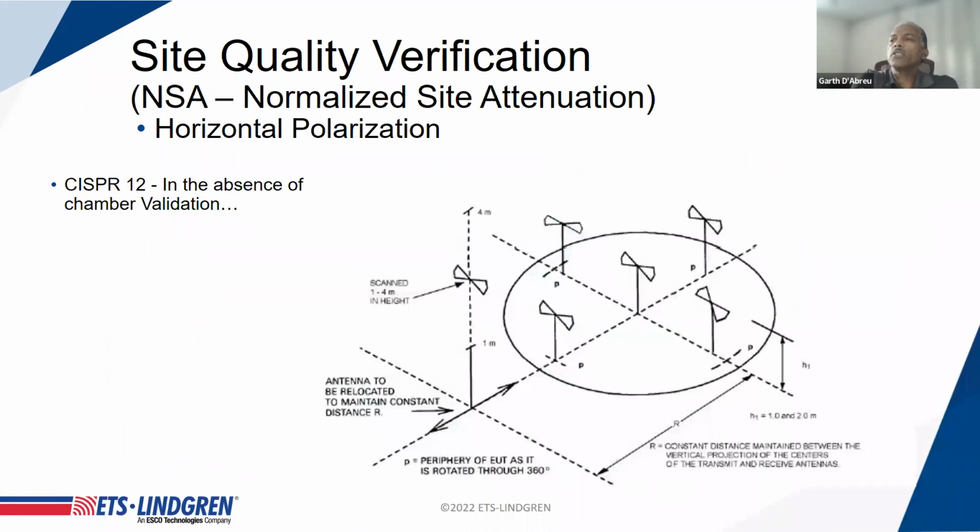The standard gives guidance on the suitability of the measurement environments, and the degree of the guidance varies by standards. Some of the commercial standards go into very great detail with very detailed procedures for quantifying the uncertainty within your test volume. This is an example from CISPR 16, which is a standard that's used on commercial electronics or consumer electronic products. And what this does is define a method of measuring the S21.